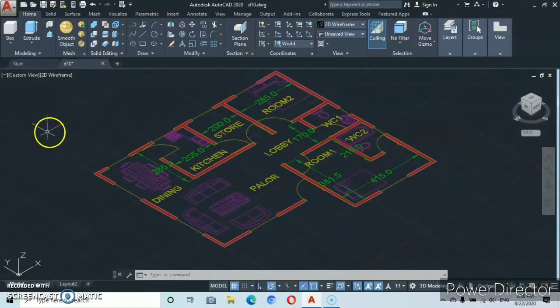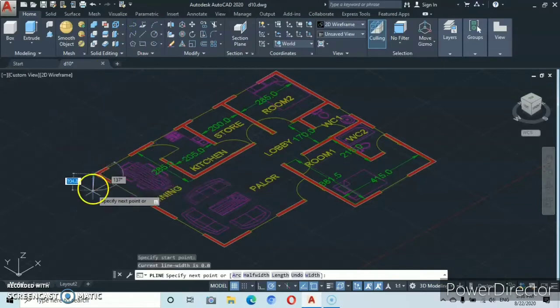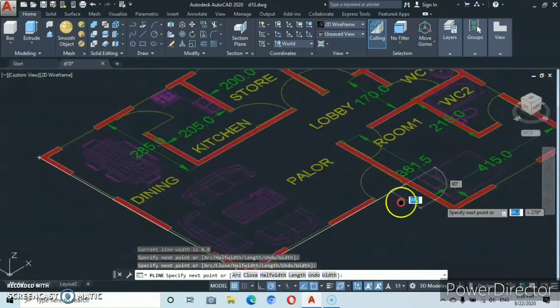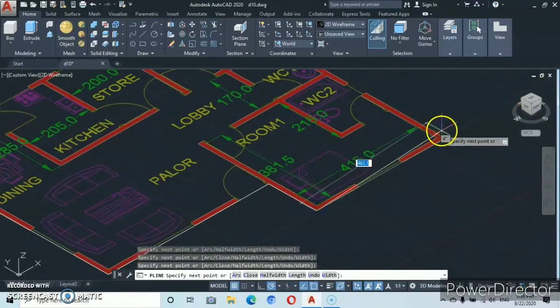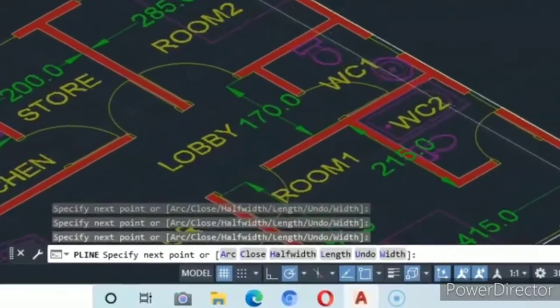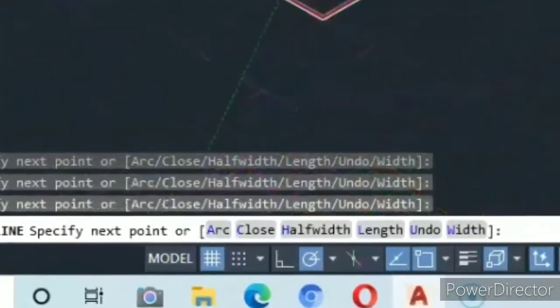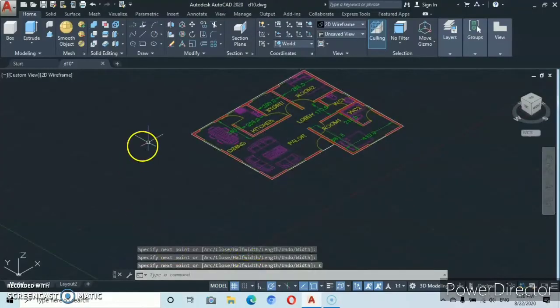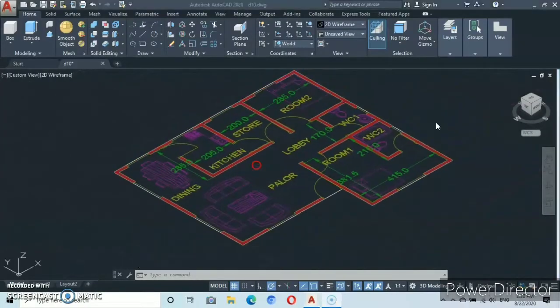Then the next thing we're going to do now is let's go to Polyline. Like I told you, we're just going to use this plan as a reference. Okay, we start from this first point here. We click by using a polyline. Click on this other point, and then let's zoom here to click at this end. Be careful. Select very carefully, and then we click at the end points. Then we'll move down to click at this other end point. Then now let's come down to the close line command, and we click on close so that this line will be closed. Very good.